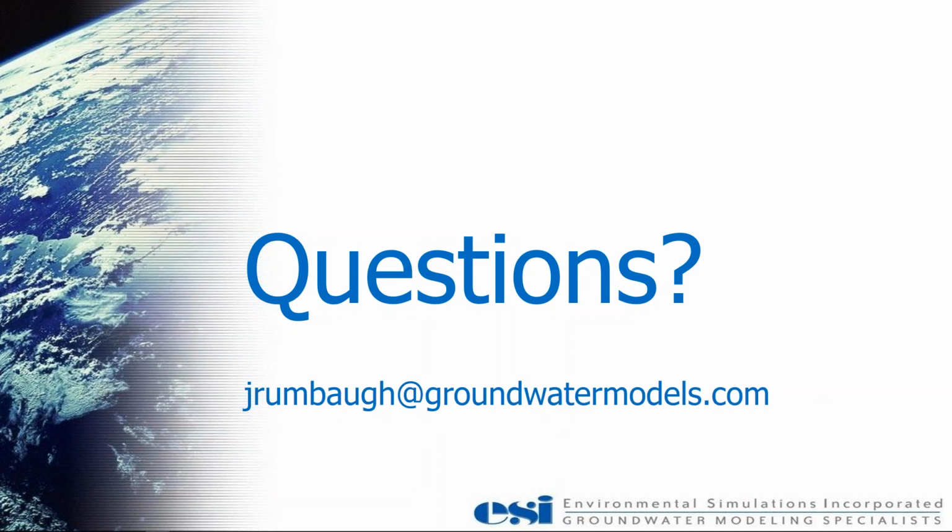We did get a lot of questions this morning, and while I'm letting you think about it, one of them was, does Groundwater Vistas allow you to use PEST with MODFLOW 6? Yes, it does. All aspects of PEST work with MODFLOW 6 just like it does with all the other versions of MODFLOW, including pilot points. The only real distinction would be if you're using a regular MODFLOW grid, so a row column layer type grid with rectangular cells,